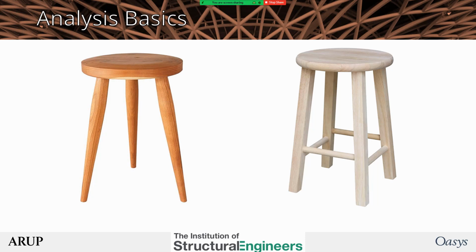Now, when we build analysis models, we tend to assume the structure will be perfect, the floor is smooth, the stool is even, every leg is fully in contact with the floor. Reality is not so neat. Structures will often work the way we design them, so long as they have enough ductility. In the case of the stool, the connections may have a little bit of flexibility if they're not glued, the top may warp a bit, and so on.